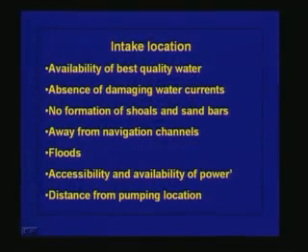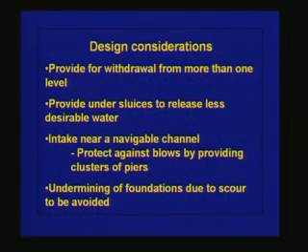Now, distance from pumping location. Sometimes the pumps may not be placed within the intake structure itself, as we have seen in some earlier diagrams. If the pumping is a little far away from the intake structure, that has to be considered, because the hydraulics of the flow, how much friction loss is occurring in the intake pipe, has to be given due consideration. Now, what are the design considerations for these intakes?